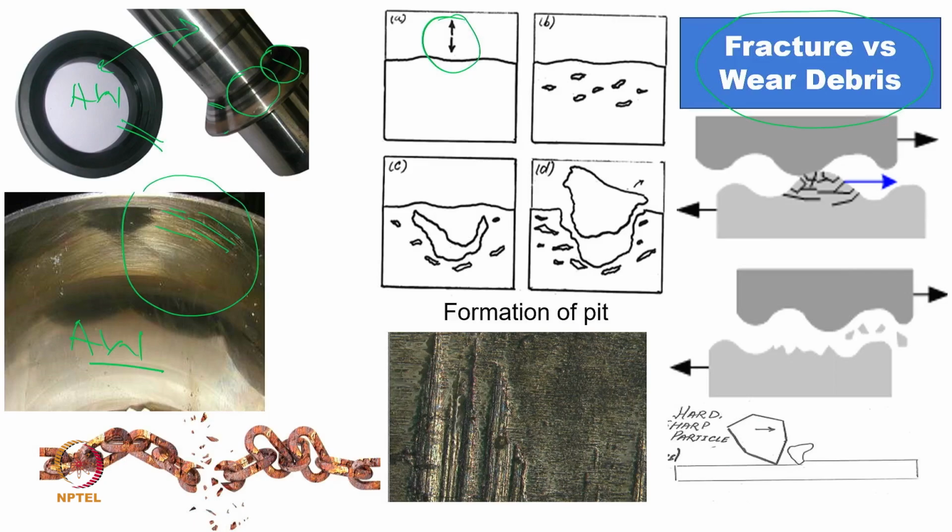In this case also we showed that there is some sort of defect in the material, and that gives some initial site for the crack formation, and then when the crack size is increased, the cracks may merge with each other, agglomerate and make a bigger crack. And slowly, because the stress intensity has increased significantly at the site of this kind of crack, it will slowly propagate to the surface